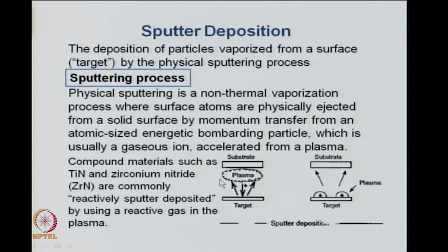So, there are two parts. First is the sputtering using ions generated from a plasma onto the target, which then sputters atoms of the target material which you want to be coated on a substrate. So, first is getting those ions or atoms out of this surface using either energized atoms or ions from a plasma, and then depositing them on the substrate.